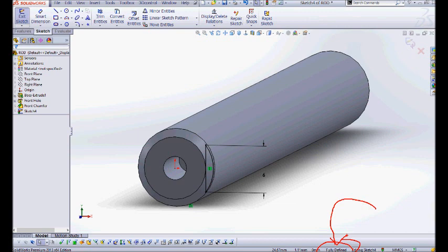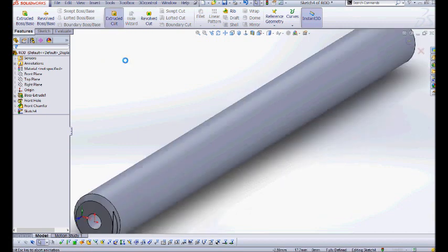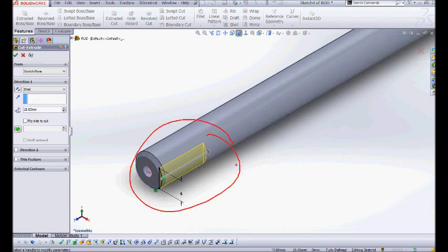The way it works is you've selected the trim tool, and you've enabled power trim. Then I hold down my left mouse button, and that's like picking up the machete. Then I slash my machete across, and when I release my left mouse button, that's the same as stopping my chop.